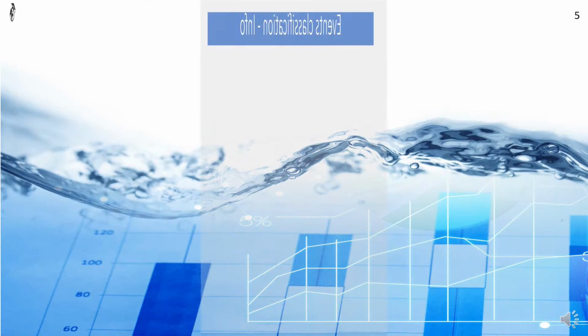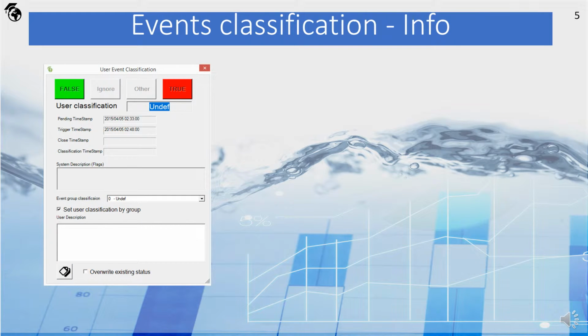This is the classification screen. The main purpose of classification is to instruct the EDS about how to learn from events. At the top of the screen there are 4 buttons. They are labeled as follows: False, Ignore, Other, and True. False means that a certain condition in the water quality should not trigger an event. Ignore means that the operator instructs the EDS system to ignore this event in the learning process. Other also means not to include the event in the learning process, but the cause of this event should be notified and recorded. True means that triggering the event was justified.